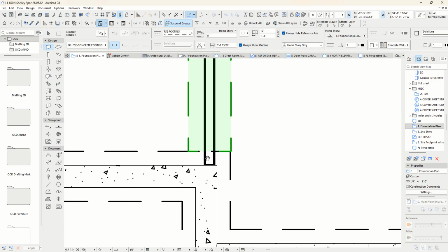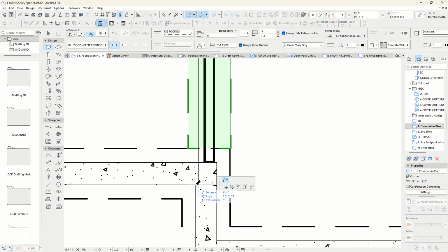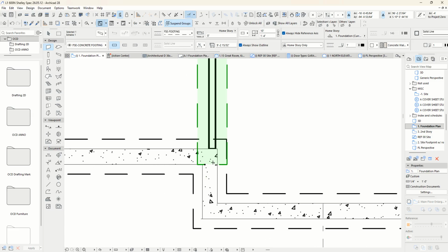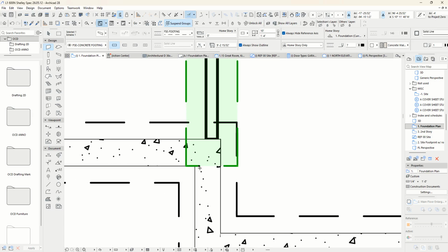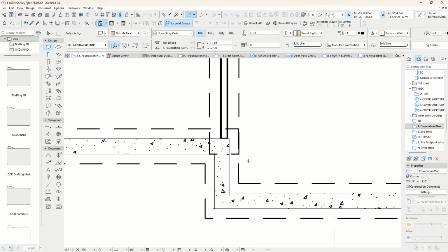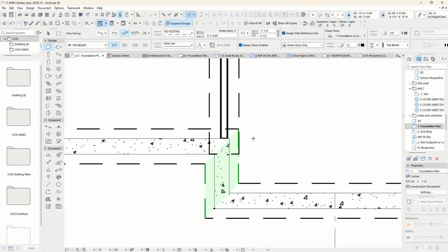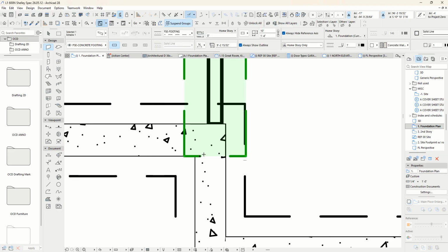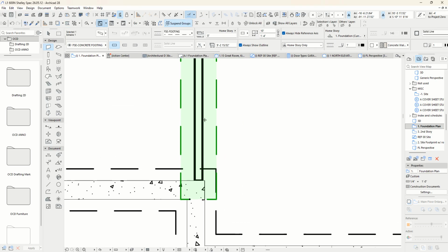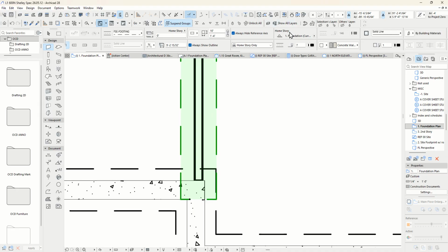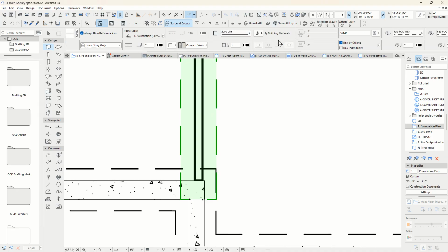If you notice, I've got my reference line here, and if I pull it down to this reference line, it still doesn't merge because this beam here stops there, so it doesn't continue across. So in this case, I need to merge with this beam, which means I need to offset this by an additional 1.25 inches. So go back to my settings up here, scroll across.